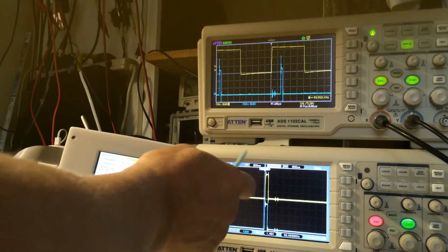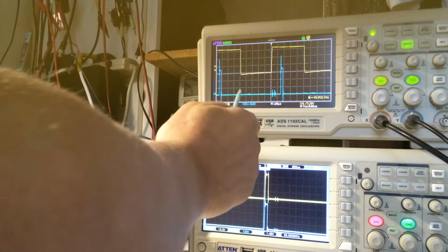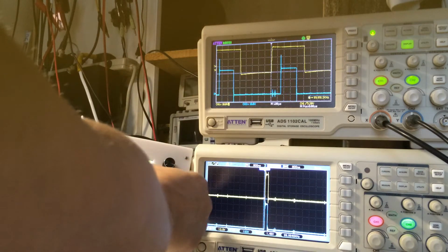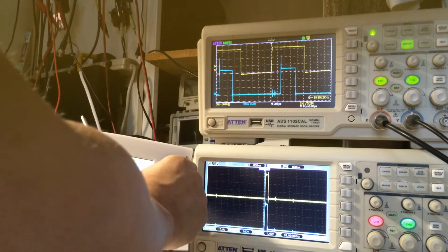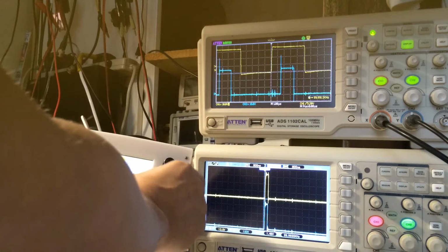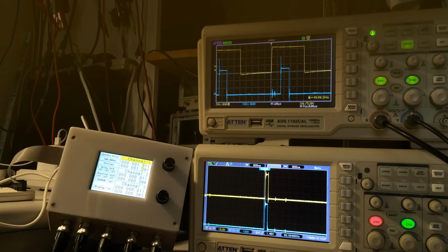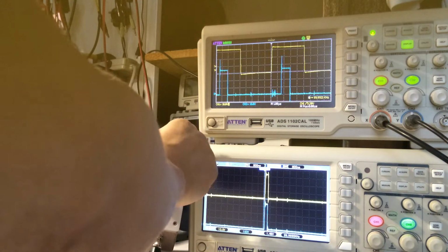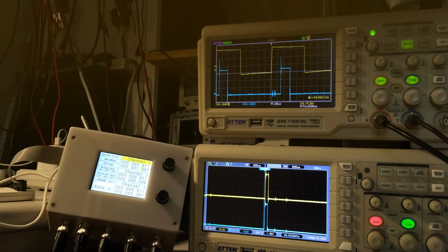Second parameter of every channel is the duration of the output signal. It can also be adjusted independently. You can see that. I just don't touch delay and change the duration. All the parameters are exactly the same as the delay parameters. It means step 11 nanoseconds, maximum quantity of steps 65,000. Both of these parameters, delay and duration, can change independently in every channel.